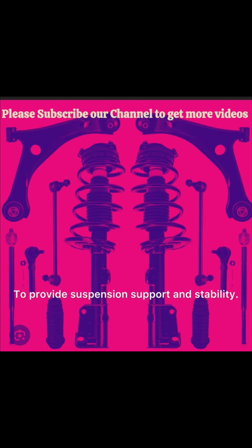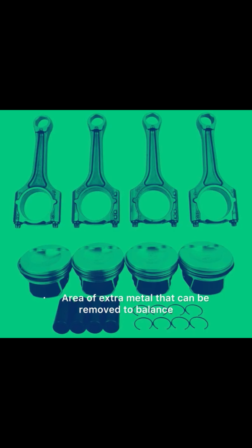3. How is piston slap controlled in an engine? Piston pin offset. 4. What are piston balance pads? Areas of extra metal that can be removed to balance. Near pin boss. 5. How does the piston expand with heat? Diameter across pin boss expands more material. Piston head expands more closer to combustion. 6. Why are some piston ring lands reinforced? Control heat expansion. Reduce wear.